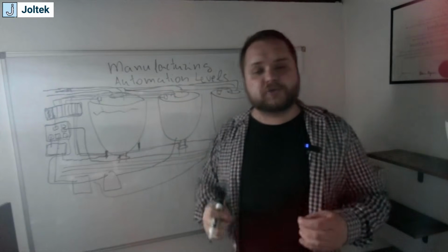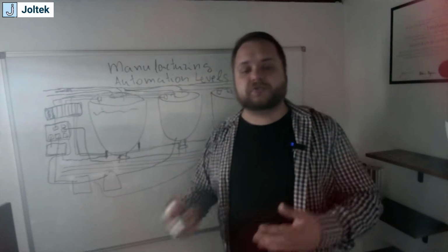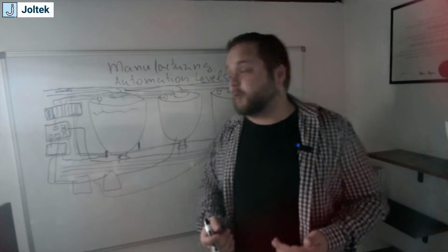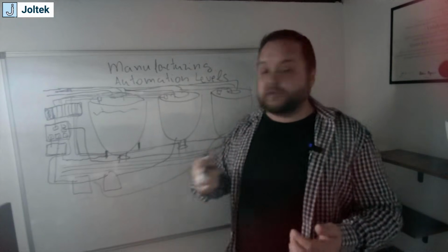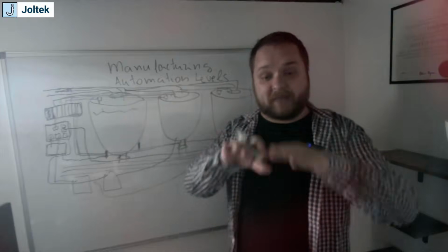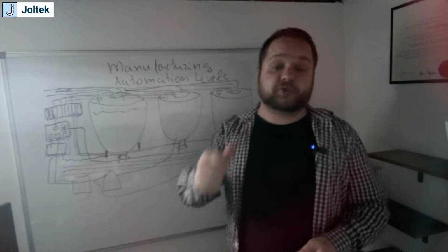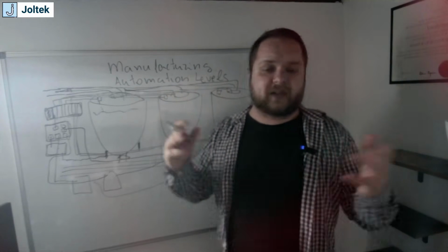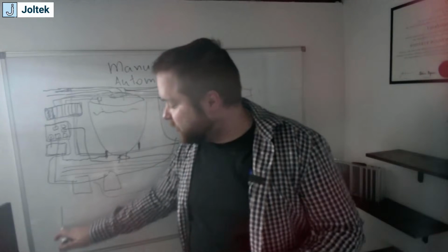Now, we've also not talked about HMIs, or human machine interfaces, and this is usually where you start needing them, right? So in the previous level of automation, where we talked about non-distributed systems, usually you can have push buttons, and a lot of them are still designed with, let's say, panels. You have an electrical panel that allows you to start the entire system, to stop the entire system, to start and stop maybe specific components. You even have lights for faults. But this is where you start to need what's called an HMI.